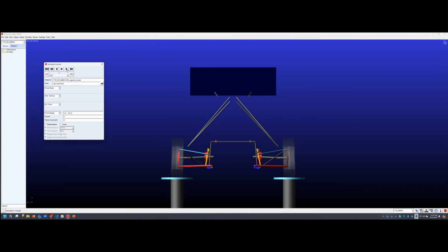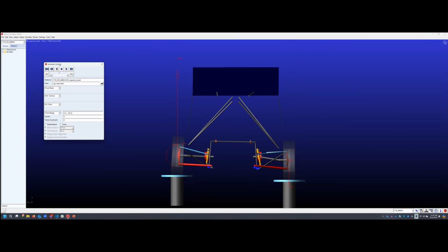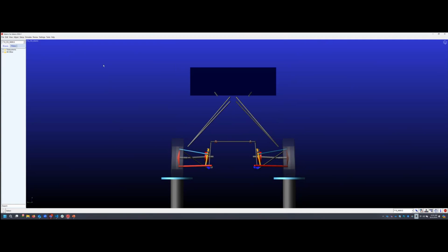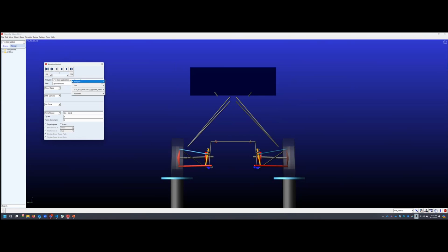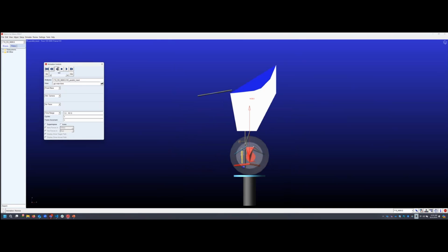And then as you can see now, in this case, our wing just slides from one side to the other, so it maintains that angle of attack, and that doesn't change. So I'm sure the aero guy was very happy with that. And similarly, in parallel wheel travel, it just basically goes up without changing any angle for the wing.